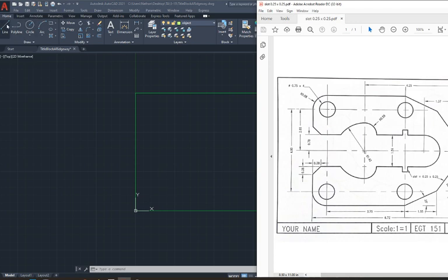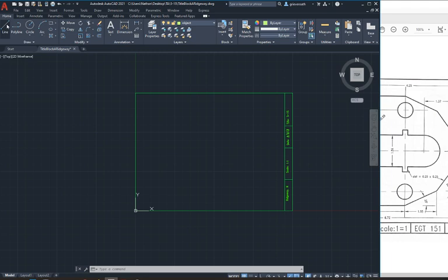So what I'm going to do is start with a line on the object layer. I'm going to start close to the bottom. I'm going to click. I'm going to turn ortho on with F8. And then I'm going to make this 6.72 long. I'm going to put a couple of zeros in there. The reason I'm doing this is because if I don't specify, it might be 6.7216 something. But with these extra zeros, I know that I'm not going to get any strange leftover numbers.